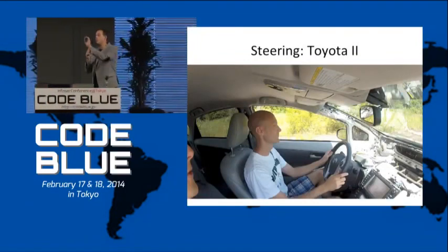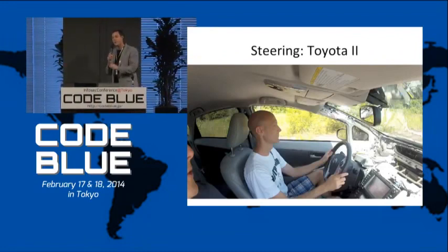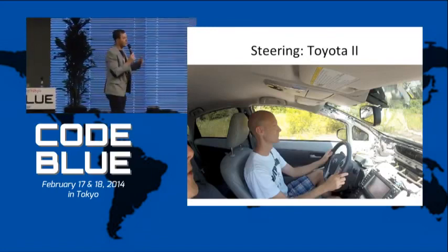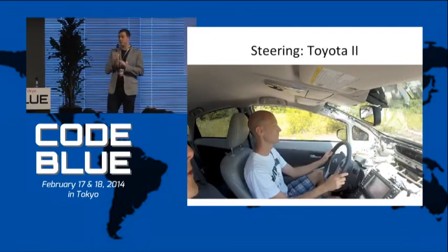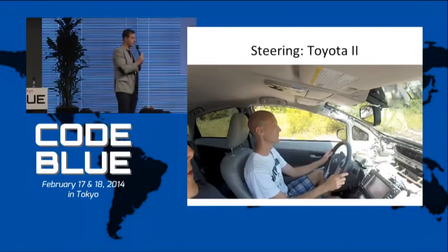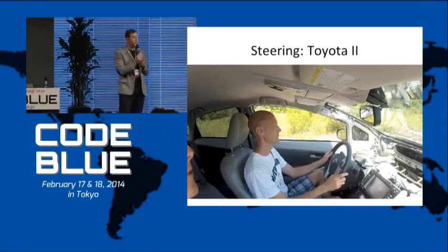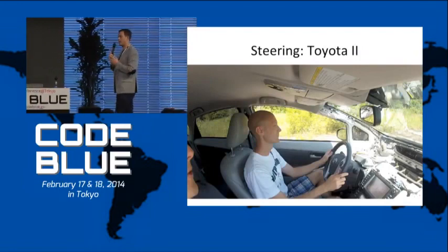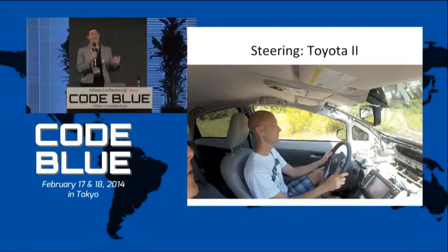But the reason the wheel didn't turn fluidly is because there were some safety mechanisms on the Toyota Prius. The Toyota Prius would not let the wheel of the car turn unless the car was going less than 5 miles an hour, it was already in the auto parking mode, and the car had to be in reverse. So how did we get it to turn the wheel violently when we were actually driving 25 miles an hour? Where do you think they read if the car was in reverse, the speed, and the parking mode? They read it off the CAN bus.